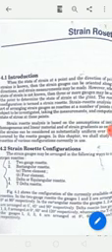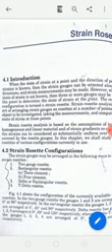In that, the strain rosette is based on the assumptions of isotropic and homogeneous material. Already you know what isotropic and homogeneous are. Isotropic means, iso means same, tropic means the property is the same in every direction. Homogeneous is nothing but the same material throughout the body, or we can consider the material as the same, right?